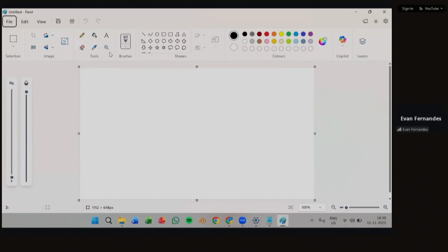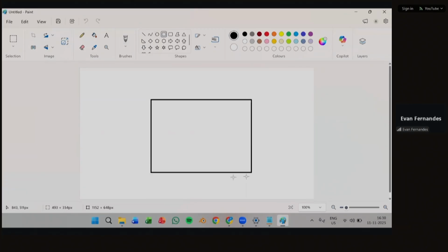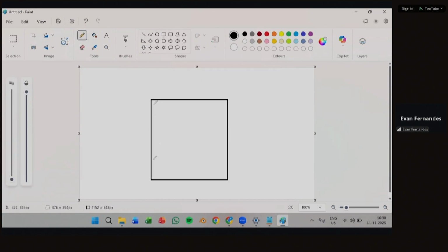So in our particular case, the one that we've copied now, the cavity case. So what is happening in this case is you have, this is your domain. Okay, you have walls, this part, and this part. These three are walls. Okay, it's a 2D case, so you don't need to bother that much in the Z direction. So these three are walls, and the top one is a moving wall.